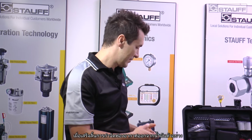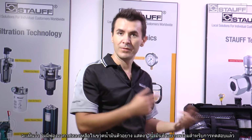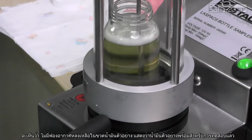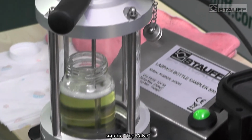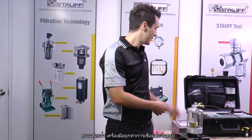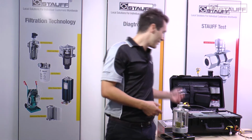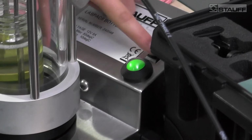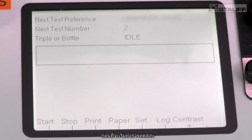Once we finish removing all the air bubbles, so there's no more bubbles down the bottom, so now we are ready to turn it off and then commence the test. So we turn the bottle sampler off, open up the top valve, change the handle to pressure mode. When the machine's already set, so make sure the machine's turned on, and then start the bottle sampler in the pressure mode. Nice.